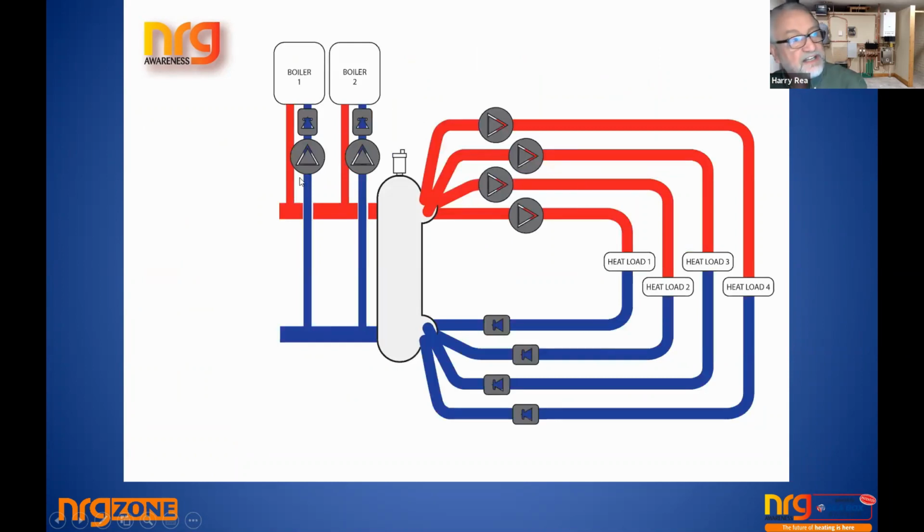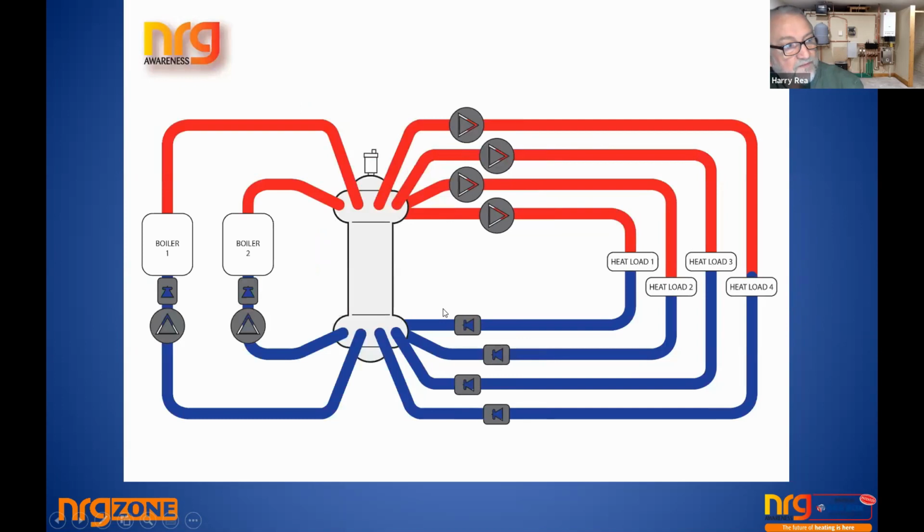So ultimately, if you were to look at what might be a great system, if you had a low-loss header that had multiple connections and they didn't have to go through a big pipe, that they were all coming from the same place, you might say, so you've got a bypass, and now none of the T's affect any other T. That would make sense, wouldn't it? It wouldn't be a viable product, though. So certainly this spacecraft looking thing might be, in theory, a very good idea, because again, no one zone is affecting another zone. You've got a completely open circuit. So all of that seems to make sense.